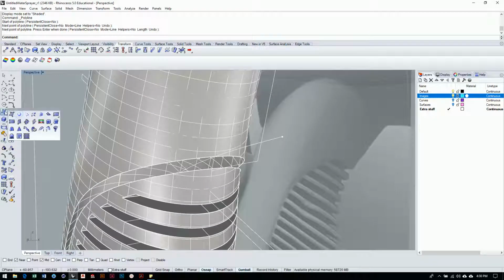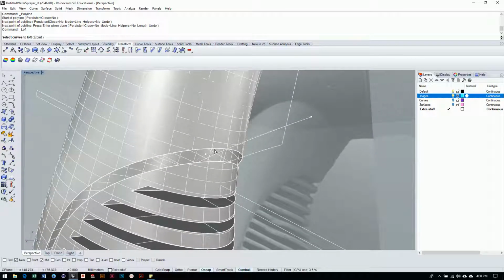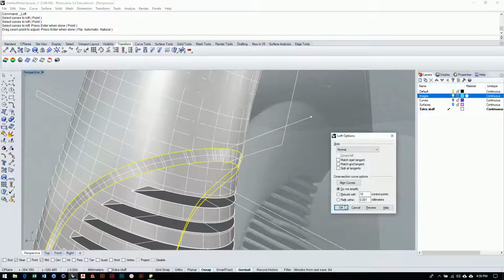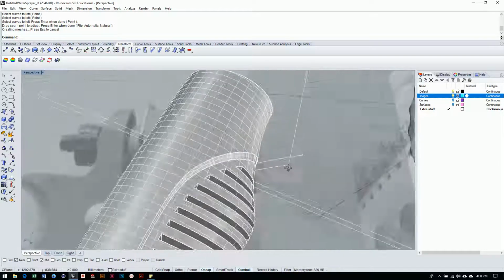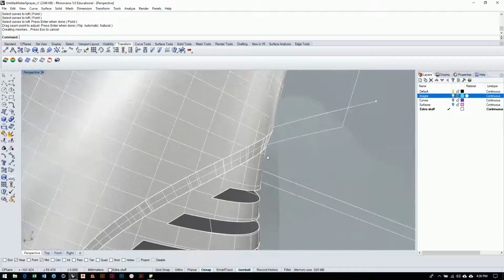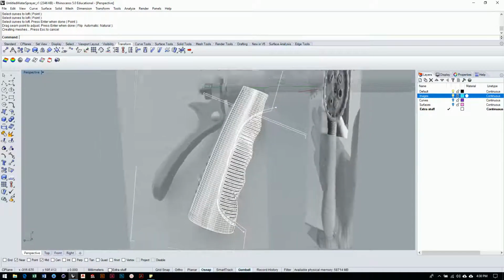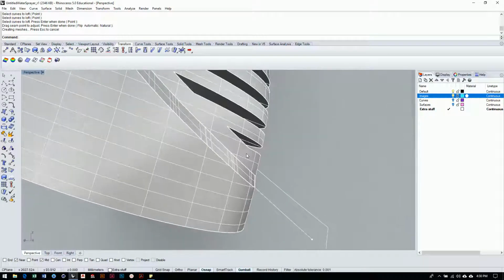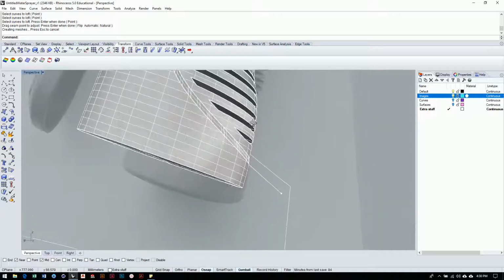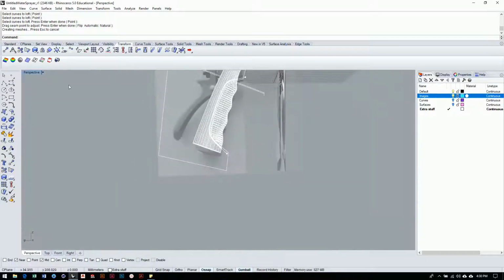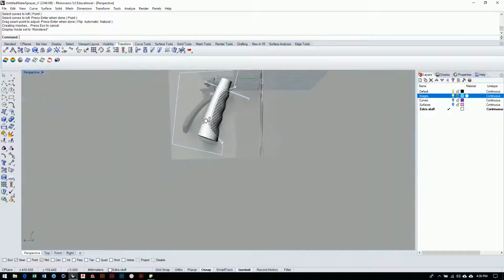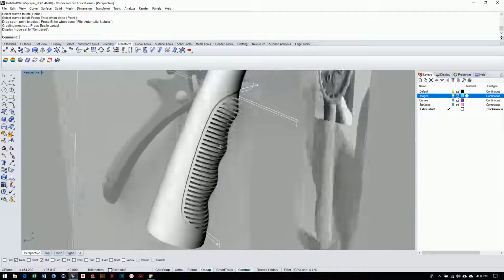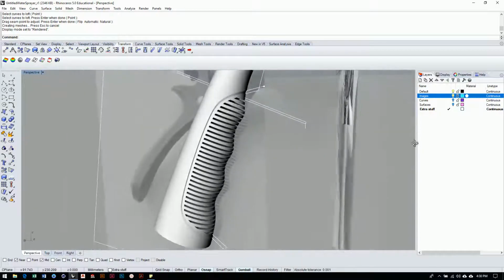And you know what I can do? I can just use a loft here. I can go loft. 1, 2. There we go. Connect that together, and then you get this cool little scalloped edge here. You get this little kind of chamfered edge detail thing going on. Not exactly the way that the actual one comes out, but pretty close. So when you look at that with your rendered view, you see the difference. It gives you this little cut, makes it look cool. So that's going to be that, guys.